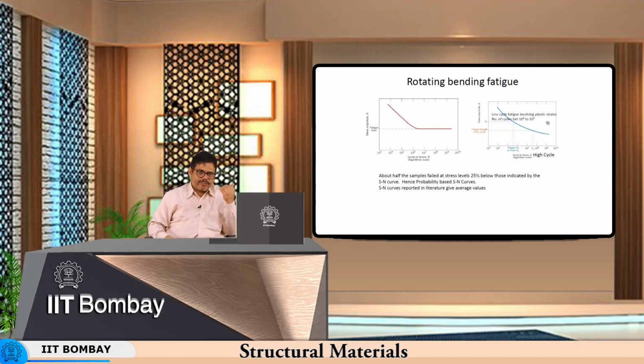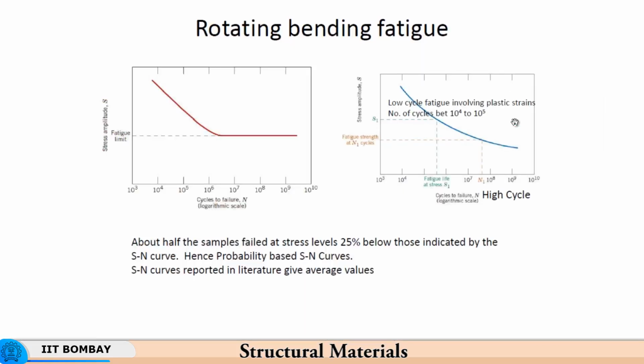There is no crack propagation as such, because when you have cyclic stress in the elastic loading, the growth of defects is extremely small. The growth of defects is extremely small, and therefore the material can continue right up to failure. That is the reason why this line becomes absolutely horizontal, independent of the number of cycles to failure, and this is called the endurance limit.